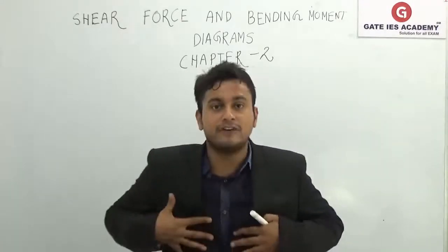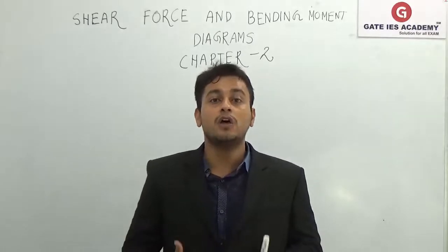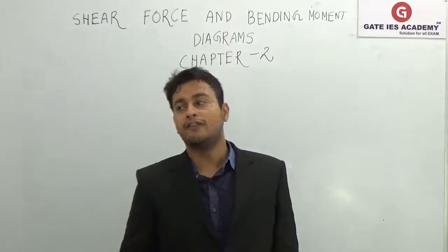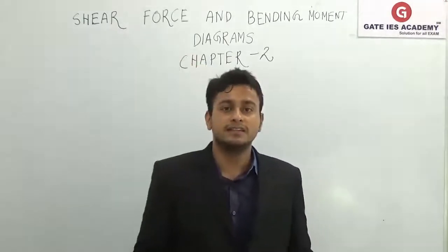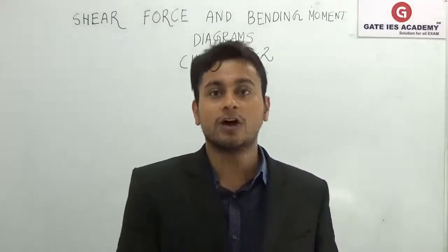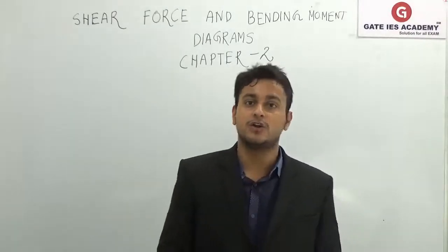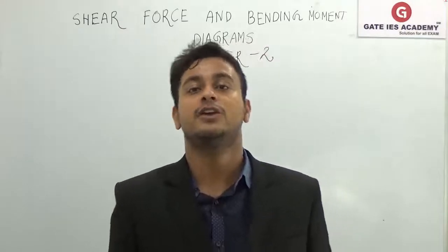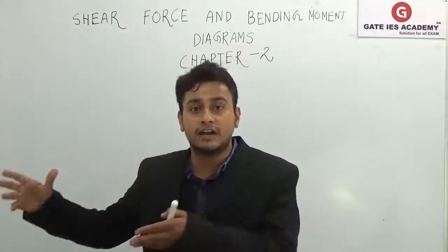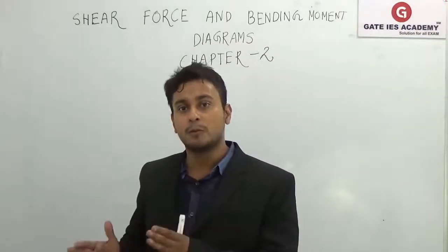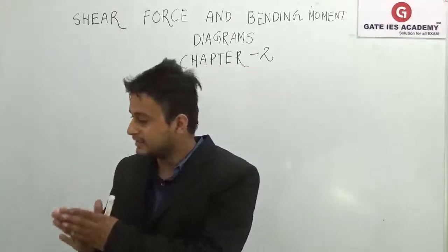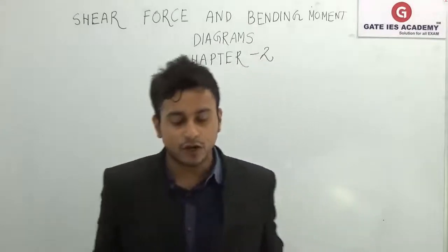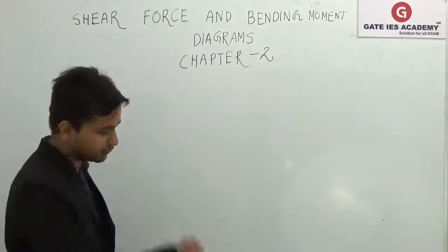Yes, I am standing, my weight is there, I am standing on the ground, so there is the loading which I am giving on the ground, that is my dead load, and if someone is hitting me on the top, there is the live load on my body. But can you see my joint forces? No. Similarly, on a beam you cannot see the internal forces, you can only see the live loads and the dead loads, and the shear force and bending moments are the net internal forces of the system. So I'll tell you what is actually shear force.